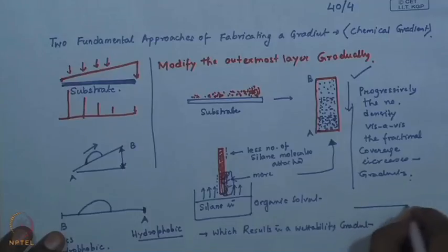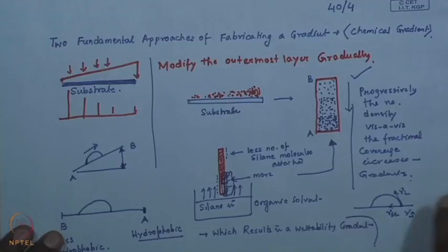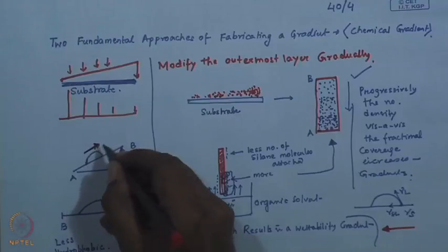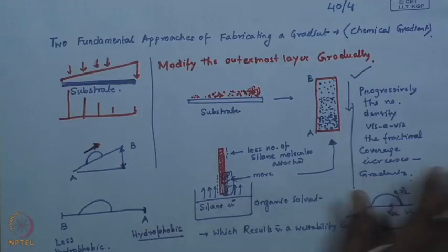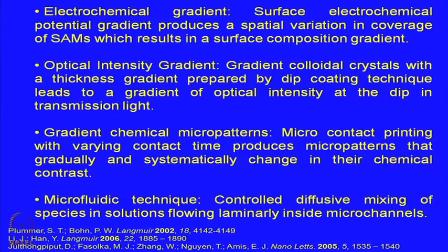If you draw a drop in the Young's configuration, we always regard this as gamma S, gamma L and gamma SL. However, here the gamma S continuously varied. So, there was an imbalance along the contact line, which resulted in a passive driving force for the drop to move, and if the drop size was small, the inertial effects were not very high, and this allowed the drop to move uphill against gravity. So, this is a pioneering experiment, and this has been shown by many others subsequently.